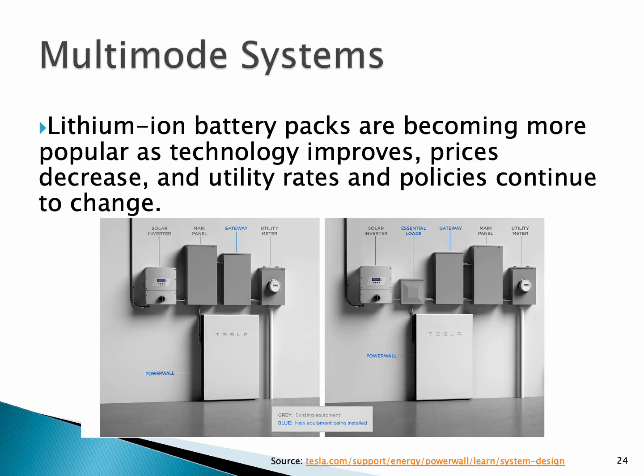We do install a number of battery-based systems throughout the year, but we install many more systems that are battery ready, meaning that we put in the array, we put in the inverter, we connect it to the grid, and it operates in a grid-based fashion. However, it has the ability, when the homeowner is ready to pull the trigger, to add batteries for critical needs. So we can do battery-ready systems where we couldn't do that 5 years ago.